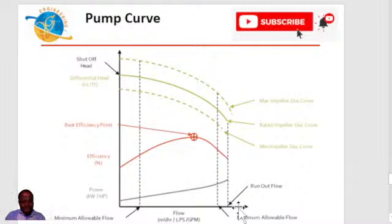So basically, on a centrifugal pump, the efficiency curve shows you the best efficiency point flow rate. That is the flow rate at which your pump has the maximum efficiency. If you are running the pump further away from the best efficiency point, you know that you are already operating the pump away from the maximum efficiency.